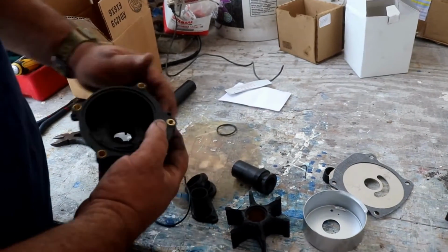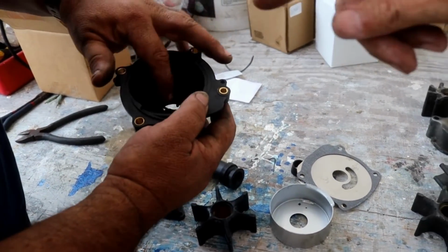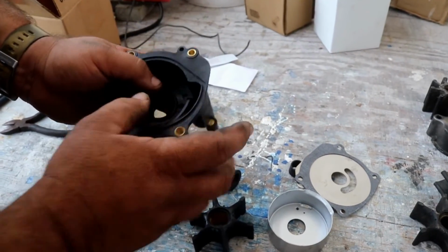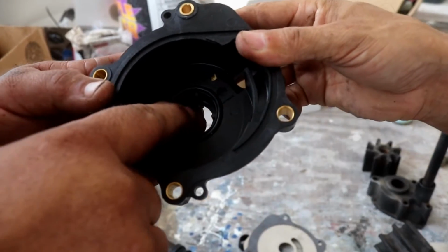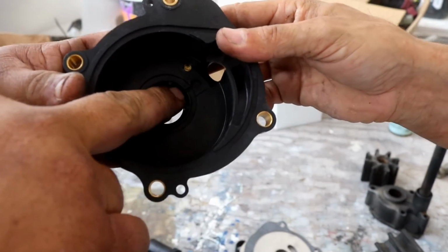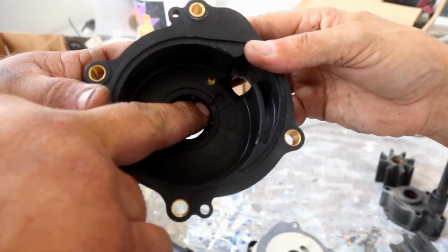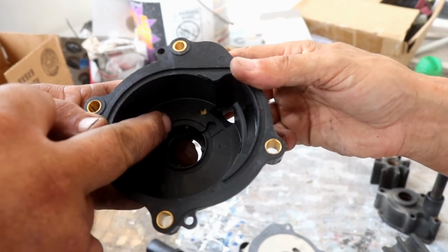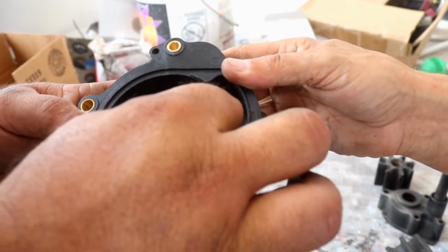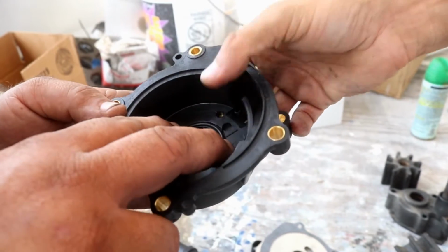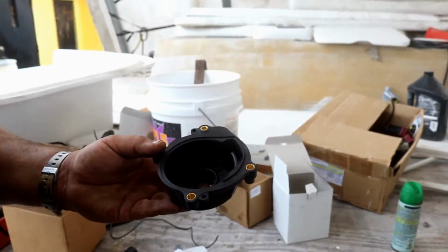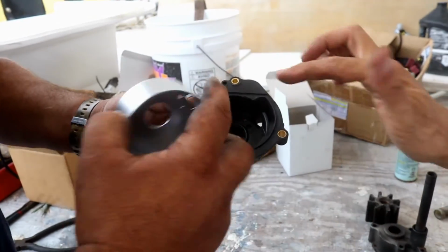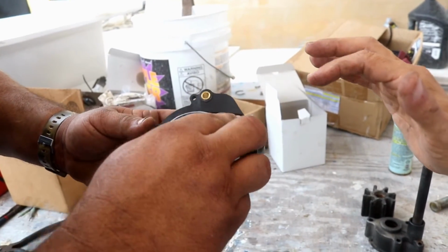But people tend to forget you have an O-ring that goes in here. What I do is put grease only half, because if you look here, there's a weep hole. If you put grease in the weep hole, you'll cause an overheat. So you only put grease down here. The only reason I put that grease is so when you flip it upside down, it doesn't fall. Then once you put the grease, you put the housing grease around here to hold the housing, so this doesn't happen.